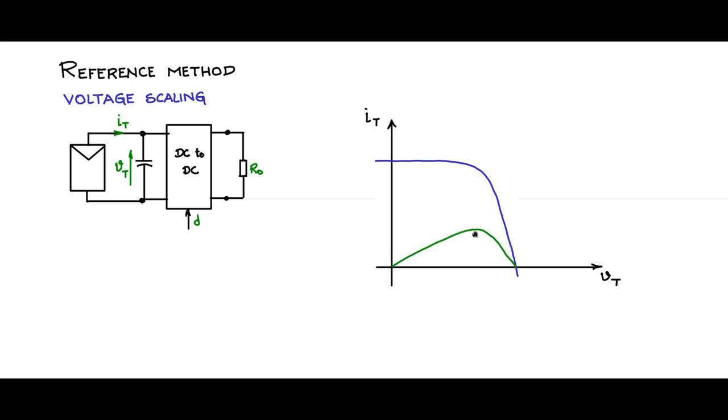The maximum power point value also will change, but it will be within a certain band. It will be within a certain band like this, and we can say more or less within this band the maximum power operating point will lie in this zone. So we will call this the VOC point, and we'll call this the VM, the maximum power voltage.